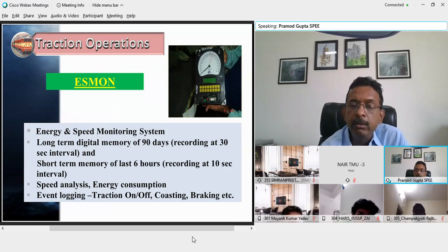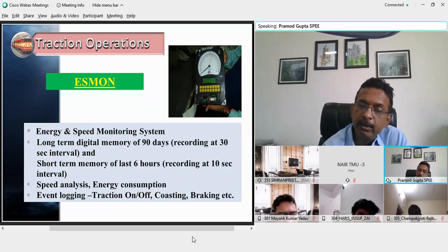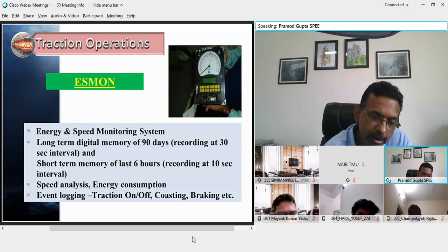First, I control the speed to such an extent that I reach the desired speed, say 1.5 kilometers prior to the point of speed restriction. Suppose there is a speed restriction of 30 km/h. That is one type of driving skill, and it is an inferior type of driving skill. The local pilot controls the speed of the train approximately 1 to 1.5 kilometers prior to the point of speed restriction, and for that much distance, it travels only at 30 km/h. So it is over-controlling of the train and a loss of punctuality.